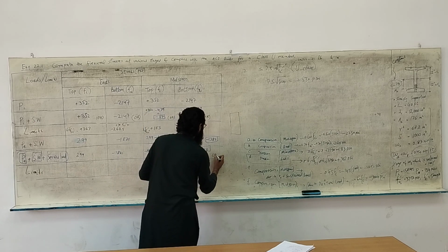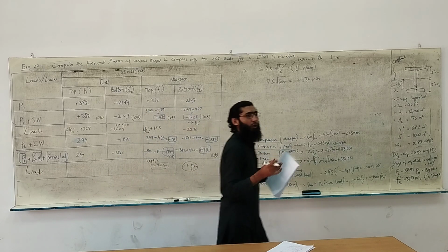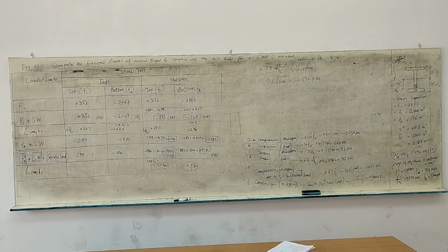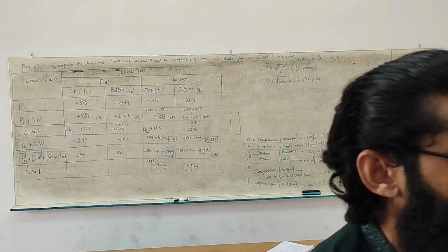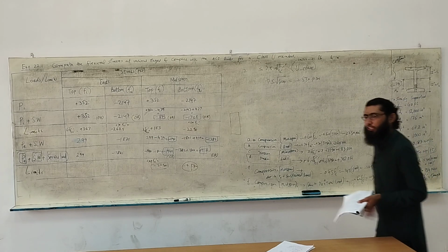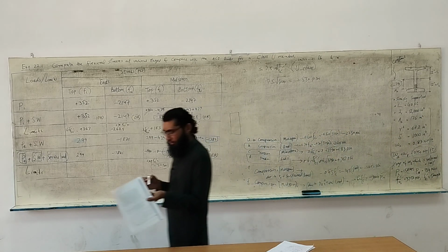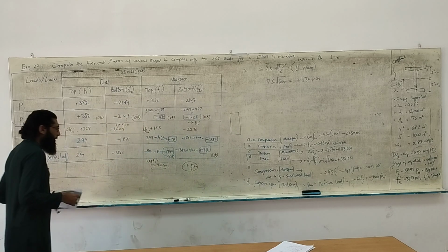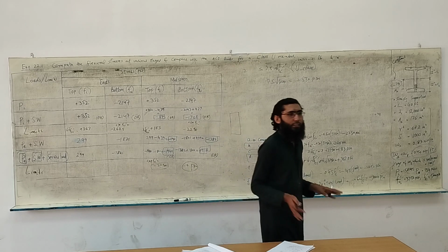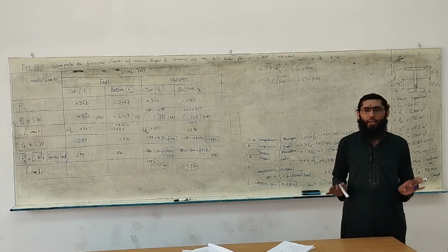So this is okay, and we have just confirmed that the member is actually a U class member. Okay, the statement already said check the limits for U class member, but we had to verify. When we have confirmed that it is actually a U class member, and it satisfies the limits for a U class member, so all the limits are satisfied. It means as long as stress control is concerned, this member is adequate.